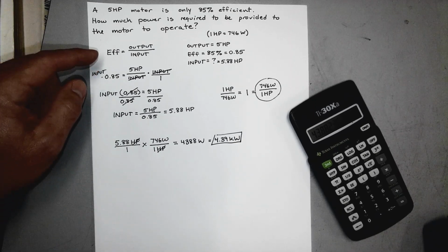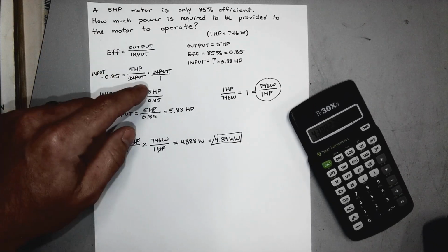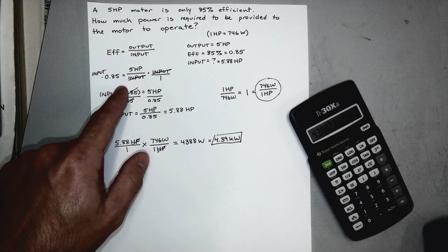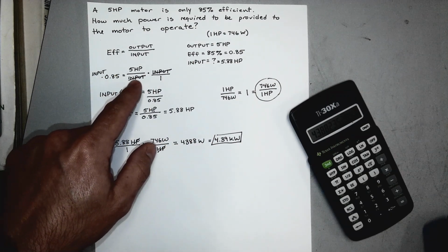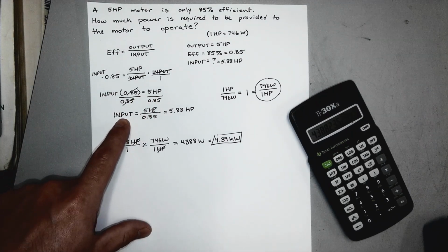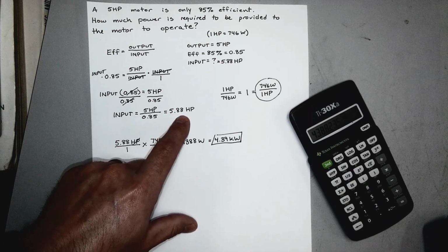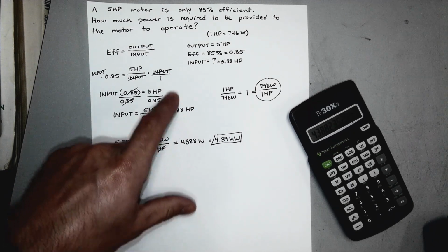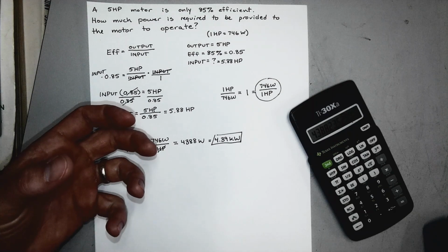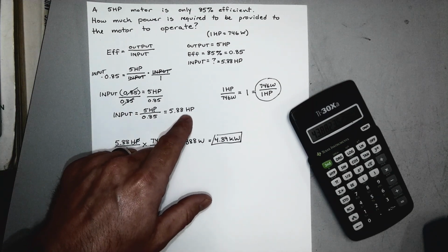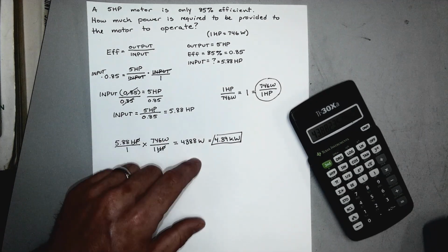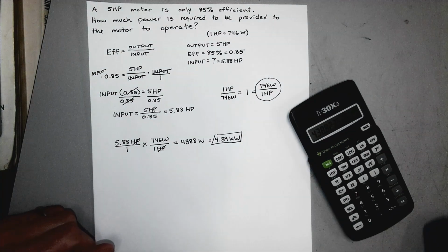All right, so we just walked through this. Remember, the first thing we do is write down the efficiency equation. We identify all the knowns, write those out, and then plug those into our equation. If our unknown is not by itself, then we need to isolate it. In this case, it was input. Then we get our value, and we have to make sure our value is in the units that the question is asking for. It didn't specifically ask for watts here, but if we're talking about how much electrical energy has to be provided to a motor, then we need to convert horsepower to watts, because horsepower is a language that doesn't work in electricity. We want to be in terms of watts when we're talking power.